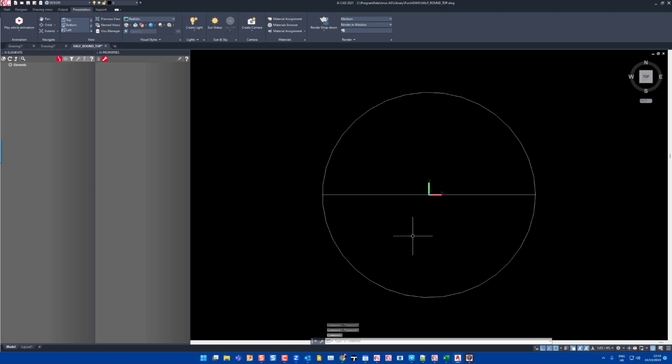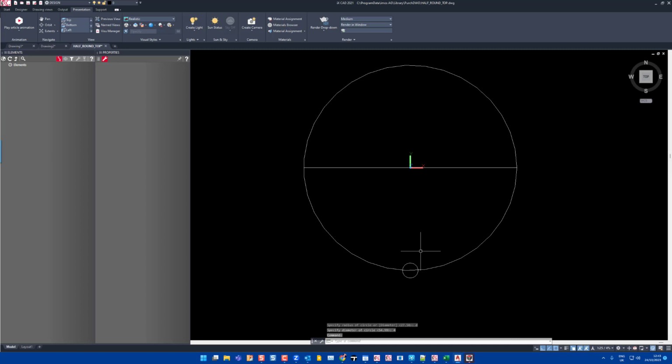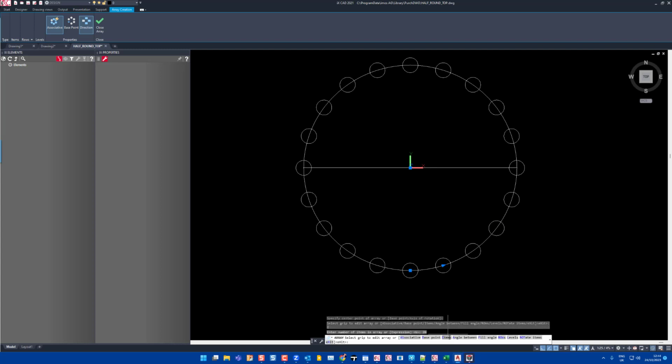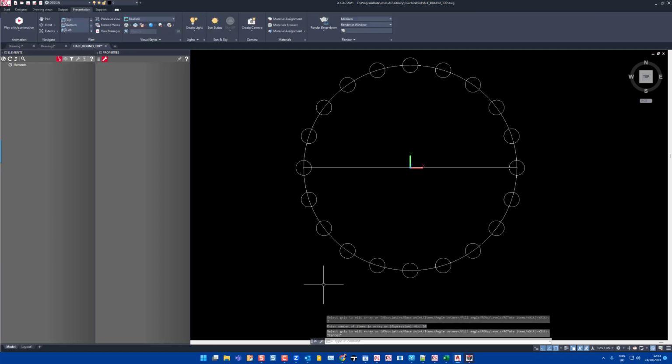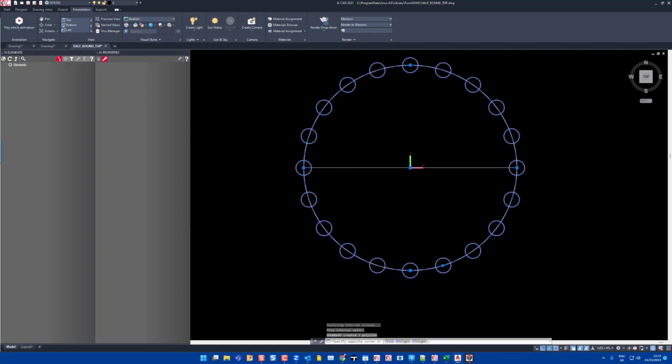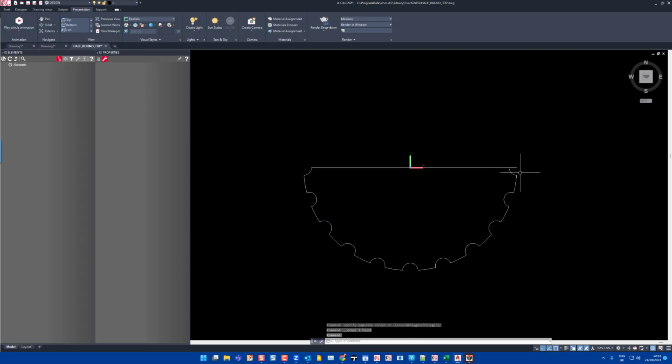I'm then going to go in and use a circle to then come in and do a diameter of 4. And then what I want to do is an array of this around a polar point, center, and I want the items to number 20. This looks okay. Then I'll do a bpoly command, pick my middle point, and I now have this detail.